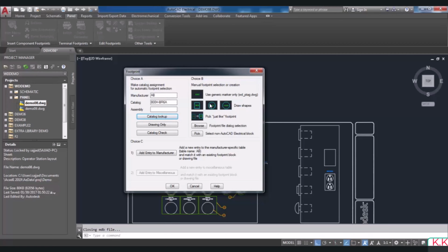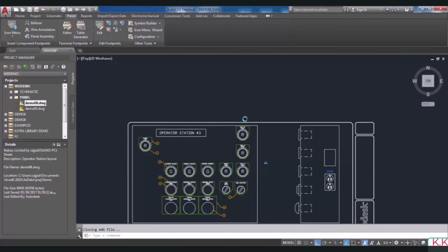The next option lets you select each particular shape, such as a square or so-called polygon, and the last option will make it possible to create a new shape of footprint similar to an existing footprint shape. In this case, because I had selected the push button, I have to choose a push button here to create a new one that has the same graphical information as the selected footprint.